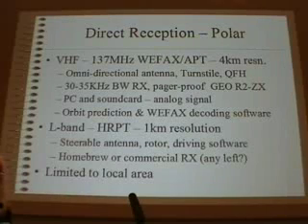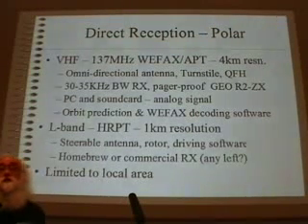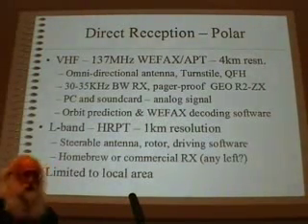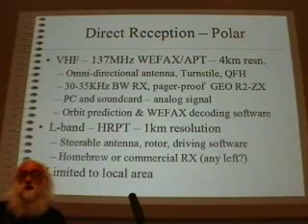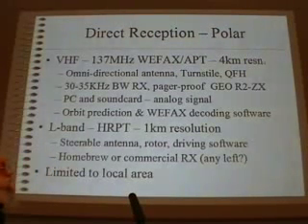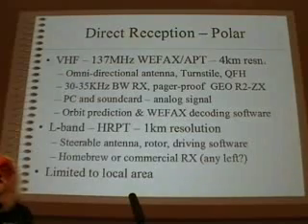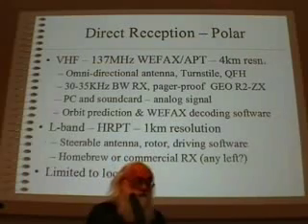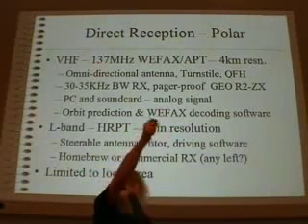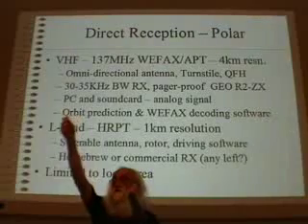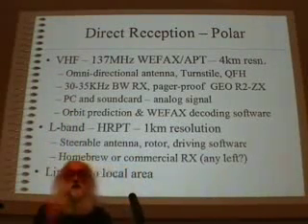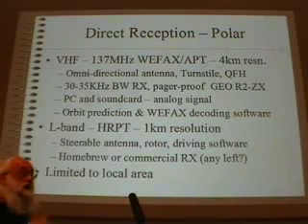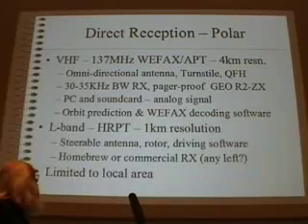For the higher resolution, the 1 kilometer resolution data, you have to move to L-band reception, which means 1.7 gigahertz type of transmission. It probably means having to have a steerable antenna. I have once seen one of the NOAA satellites tracked by somebody shouting, left a bit, up a bit, roughly tracking the arc of the satellite. But I think when you've done that once will probably be enough. So some sort of antenna rotor and steerable antenna driven from tracking software.